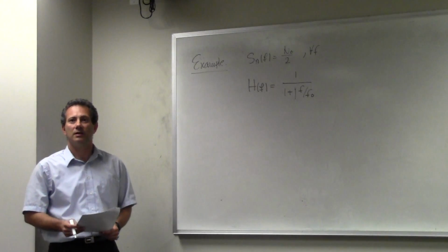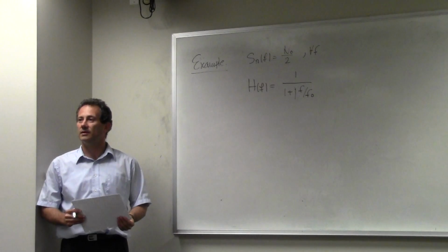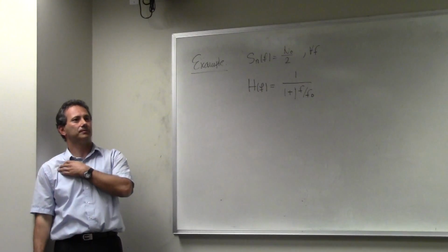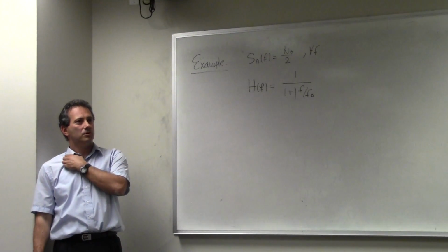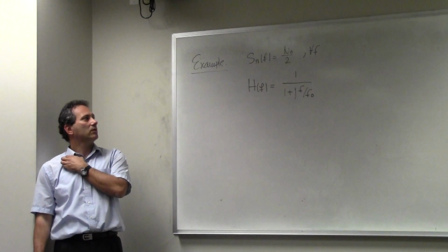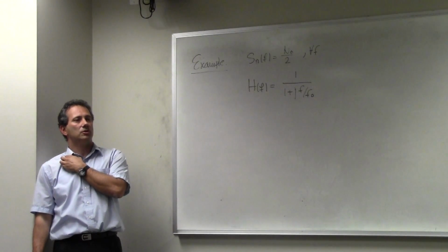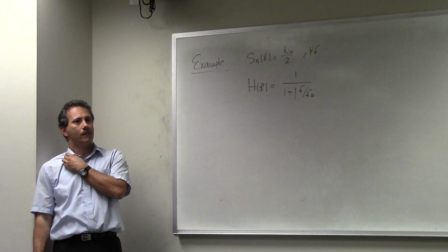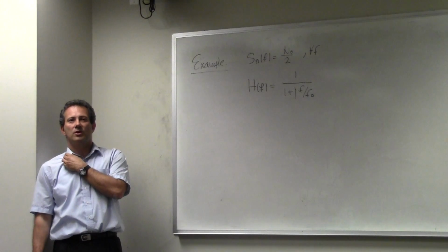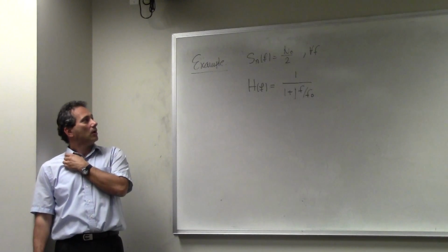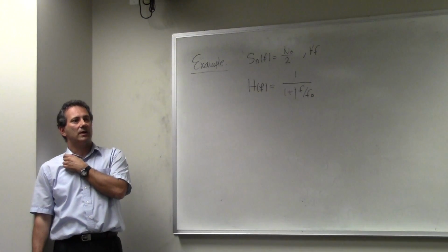You know, when I ask that, how do you check? That's what I want to see. What's the process? You test it. Like, what is the value of this for f equal to 0? 1, right? 1. So it's not a bandpass, because bandpass is 0 at 0, right? So what is the value of this when f goes to infinity?